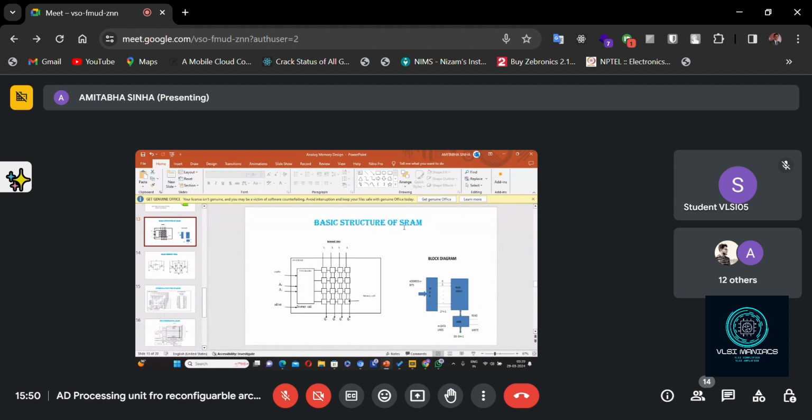This is like an SRAM; forget it is SRAM. So address lines will be there. A decoder will be there, which will decode a particular row. In each row, there will be only one column. Forget about the rest of the columns. So consider only the first column. Depending on that, a switch will be there, and that will be enabled. If it is enabled in that row, the data will be written.